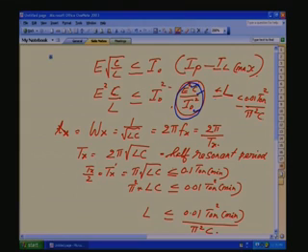I0 is equal to IP minus IL. Then the T on minimum is known, depending on the variable duty cycle, minimum chopper. Capacitor value we have initially found out from the T off minimum required to switch off the thyristor. So, from this value we can find out the maximum range of L and the minimum range of L. You have to choose L in between. So, computation will be pakka.